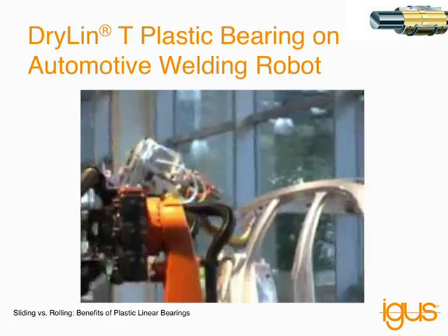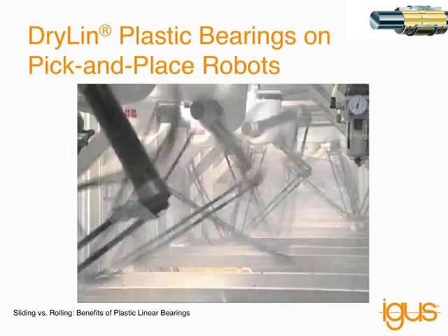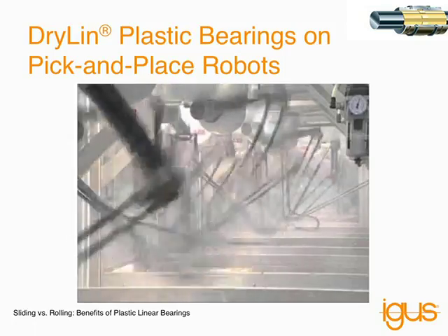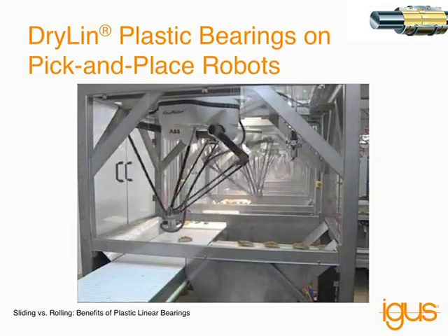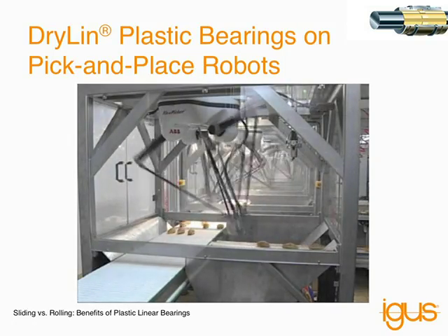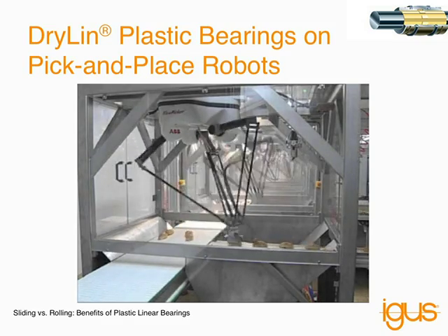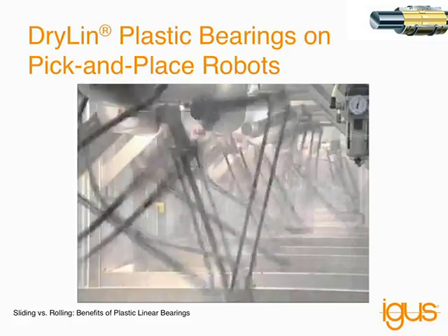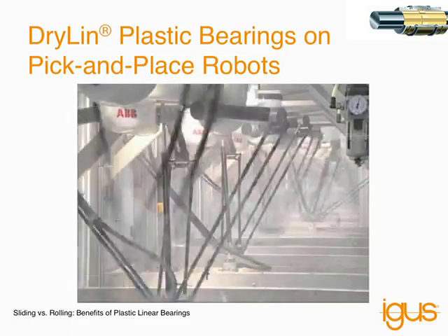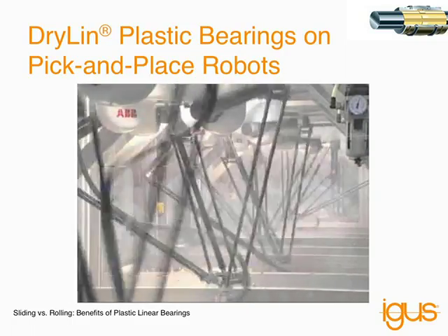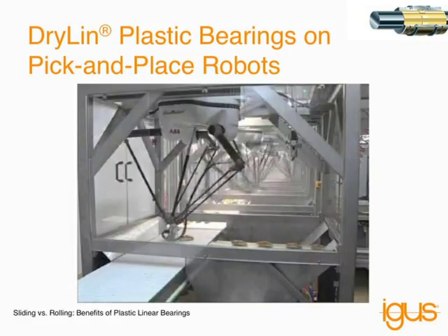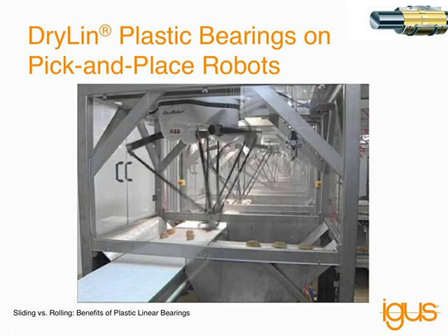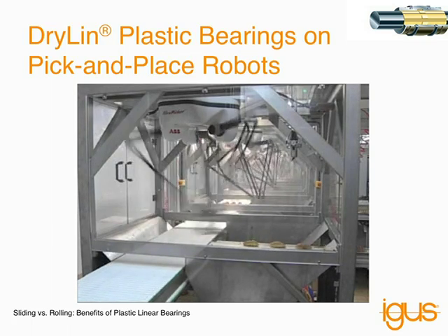Here's another really cool robotic application that's using a round plastic insert. These are flex picking robots, pick and place. Ideally, the benefit of the plastic part is, number one, there's no lubricant, again, to get on any of the parts that you're picking, but also the fact that the parts are lightweight creates less stress in the other components on the system and enables the inertia to be reduced and the overall application to run a lot smoother than it could had it used heavier parts.